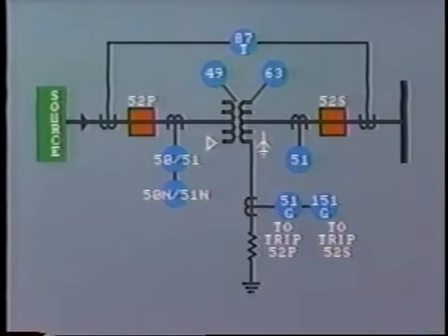First, we have the overcurrent ground relay 51G, which is connected in the grounded neutral of the transformer secondary. This is wired to trip the primary breaker and serves as backup for a ground fault on the secondary bus and feeders. Often a second ground relay is provided to operate the secondary breaker, and this is set with a longer time setting so as to allow the secondary ground relay time to clear first. Overcurrent relays are often installed as backup in the primary and secondary circuits. This overcurrent relay will act as a backup for faults on the secondary bus or feeders.